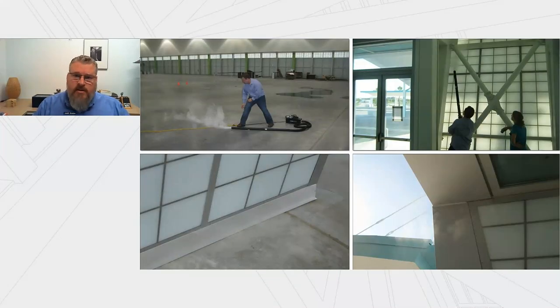Another very straightforward way is to use theatrical fog. Some people call them smoke pencils, other things. It's really theatrical fog. They don't let us burn things anymore like they used to do in the old days, which is good. This is great, especially for show and tell, or if you've got a suspect area, especially if something shows up in the IR, you can go back with the theatrical fog.